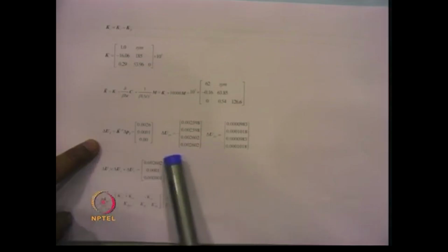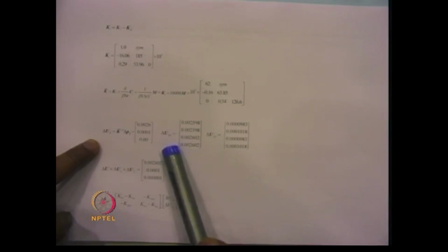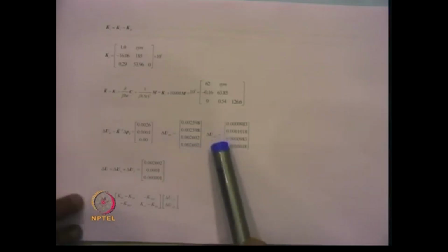From there we can find out delta Upxi and delta Upyi for all the columns, and find out finally the total displacement at the center of mass, by summing the scaled displacement delta U1 and the plastic incremental displacement delta U2.